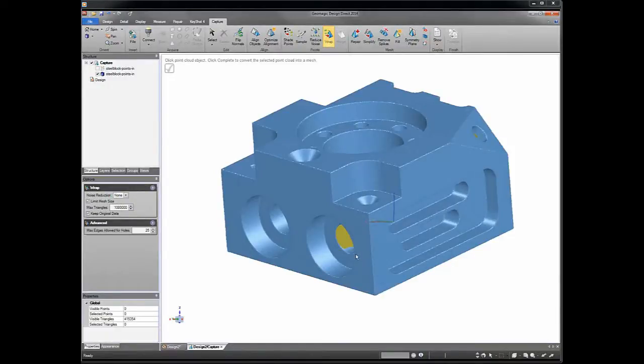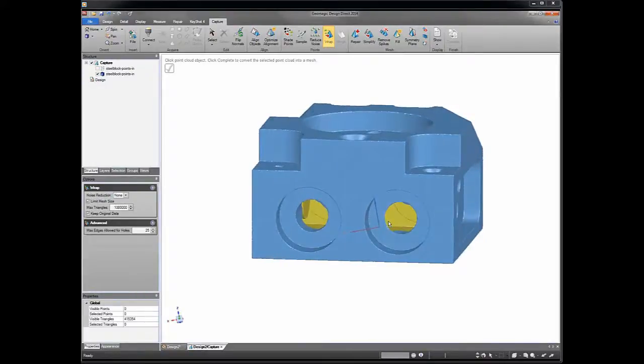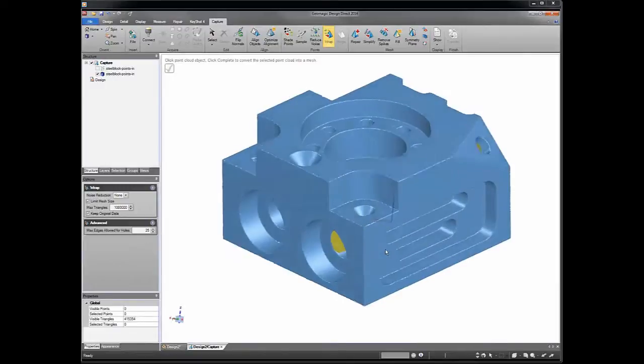The reason why you marry scan data processing with CAD tools is because that extrapolation of the missing geometry is what CAD does very well. That's the creation and extension of existing boundaries to create long internal components. There's actually a lot of ductwork, I'll call it, on the inside of this part where some of these things connect, and you can do all that in the CAD package.